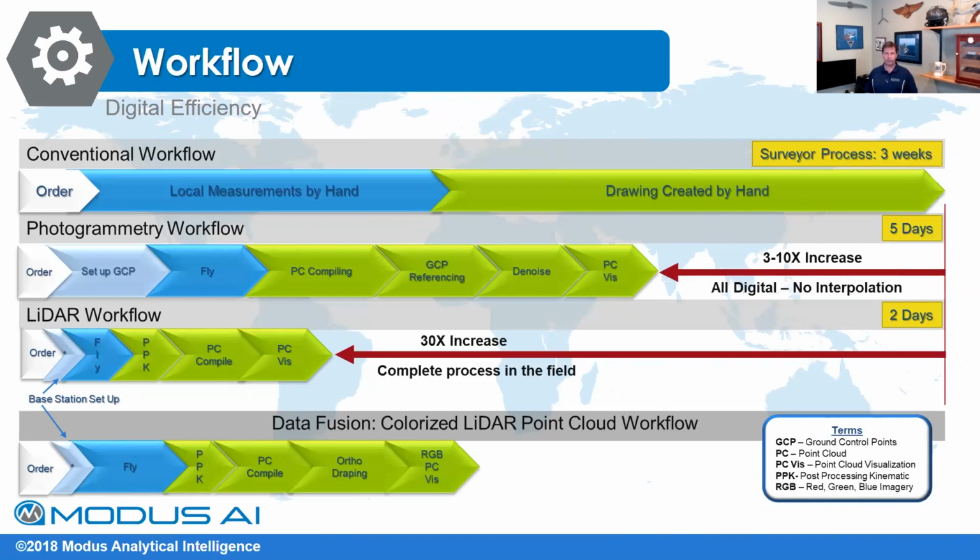With breakdown time, I had the data downloaded 30 minutes later, and had my first three-dimensional point cloud or visualization for check really 30 minutes after landing, if not less. And I had a PPK solution or a full refined solution within 4 hours from start to finish. So that was my workflow to get to visualization. And after that, I hand it off to the analyst who's going to take it through and do surface modeling and accuracy analysis and all that. So that's just one very small work case with 15 acres.